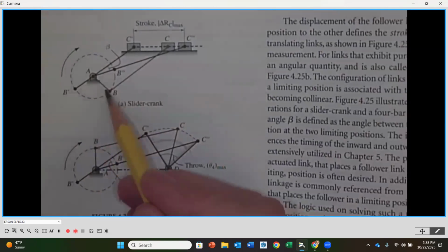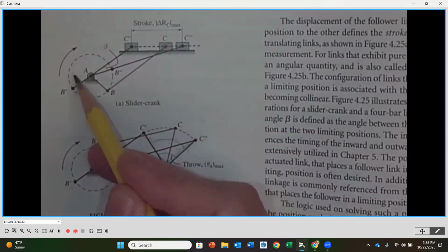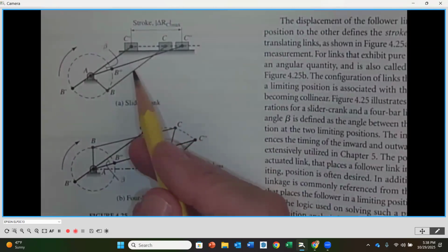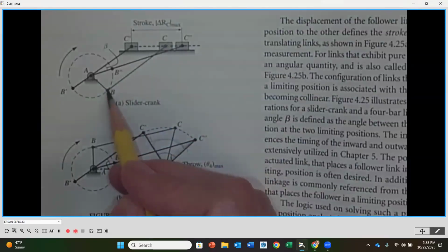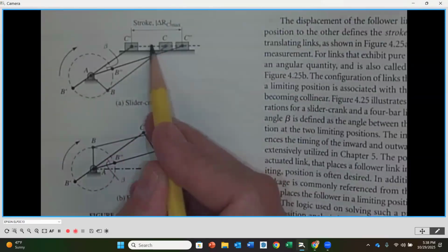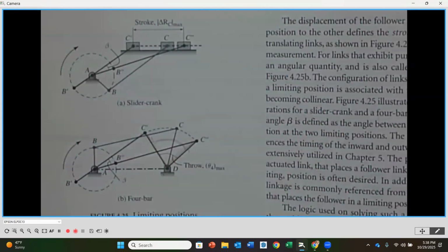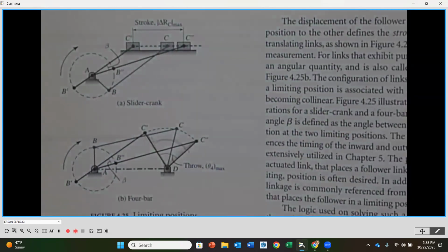The cycle is when we make one full revolution on our crank and we get the full motion of all the other links in our mechanism. So this is a random place in our cycle. They just drew link number 2, 3, and then 4 being the slider here. And this is the position of the slider, again, somewhere inside of that cycle.